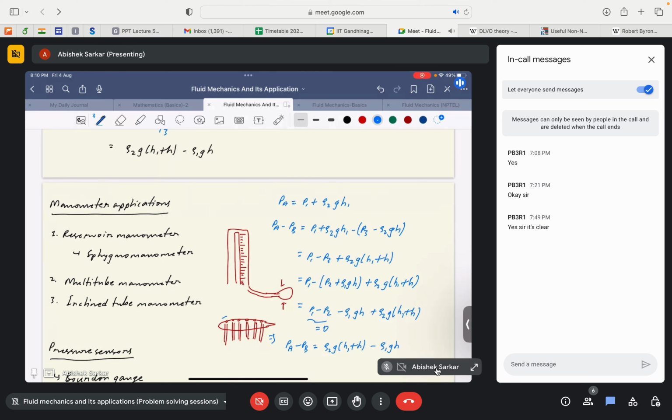because the pressure was not uniform along the surface of the airfoil, it varied along the surface, and this variation was rightly captured with the help of these pressure taps on the surface of the airfoil, which were then connected to manometers to give us the reading of the pressure at those particular points. Okay.